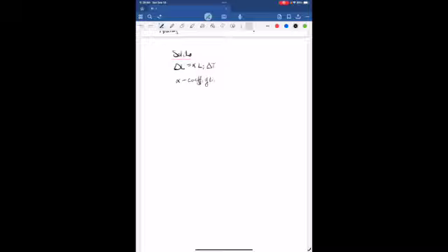And for the expansion of solids, we found a formula: the change in length is proportional to the initial length and proportional to the change in temperature, and the constant of proportionality is called the coefficient of linear expansion. And we found that this formula is only valid when the change in length is very small compared to the initial length. So this is a formula that allows us to calculate and predict the change in length of a solid.